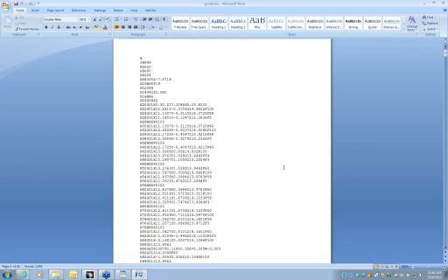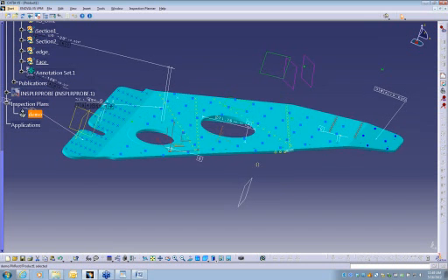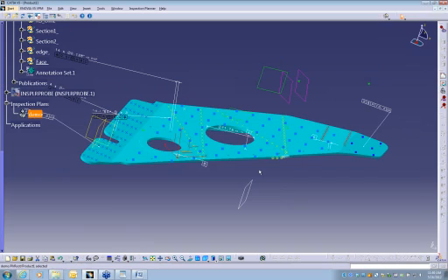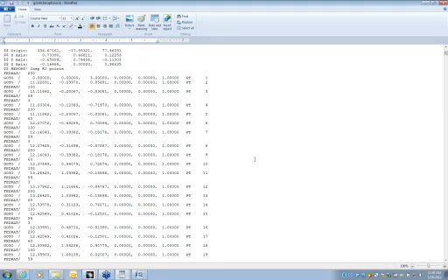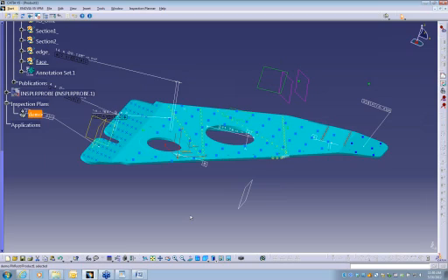G-code is kind of like DMIS. We can create a new post. This is very generic G-code, but again, we're very customer driven. If you have certain G-code, certain on-machine probing that you need to use, like if you already have the CAPS and Edges and PC-DMIS NC, we output the app source file. Some of our customers like to take this file right here and run it through their own post processor to create the G-code that's needed on the machine. So there are several different ways to do on-machine probing. We'd work with you and do the best way. Okay, any other questions?